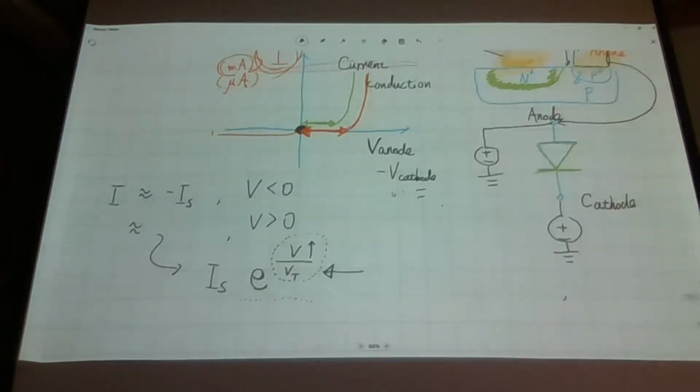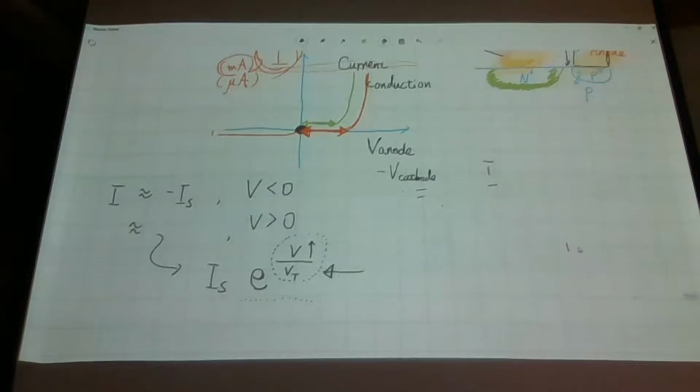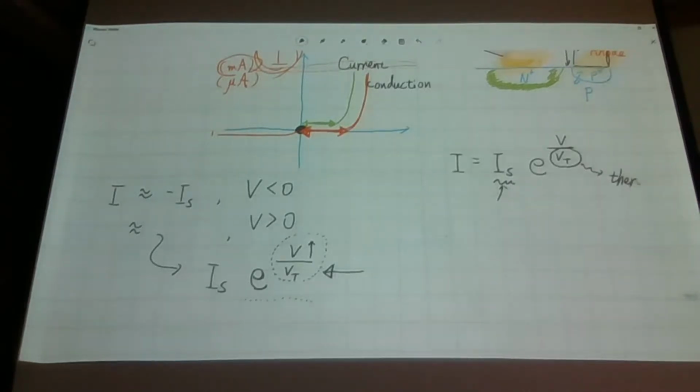So I think now it's time to talk about a very important concept about this system. Let's assume that the IV characteristics of a PN junction really follow a certain exponential variability. Please assume this dependence. And please assume a certain I_S. For example, you can assume 10 to the minus 15 or 10 to the minus 12, whatever, you can assume a certain number. So here we have V sub T, and it has its own name. Its name is thermal voltage.